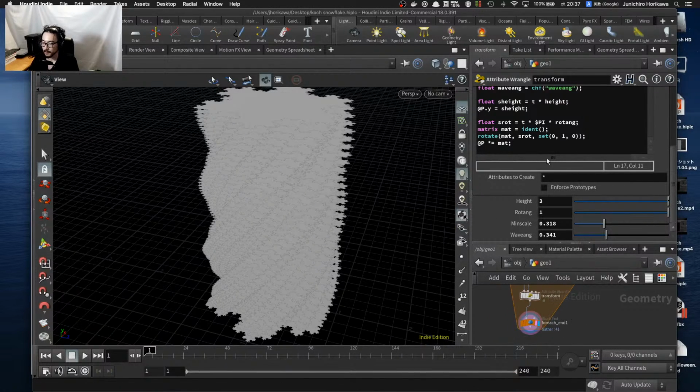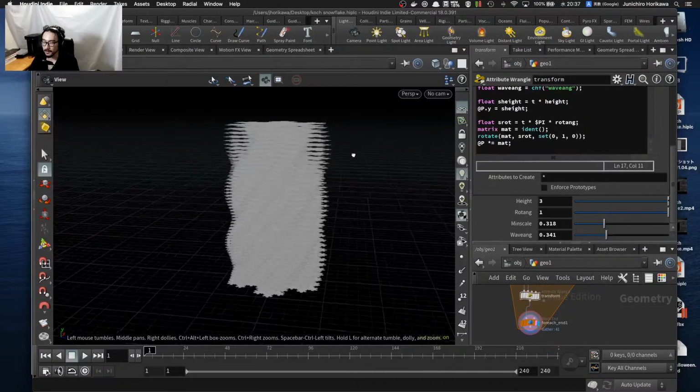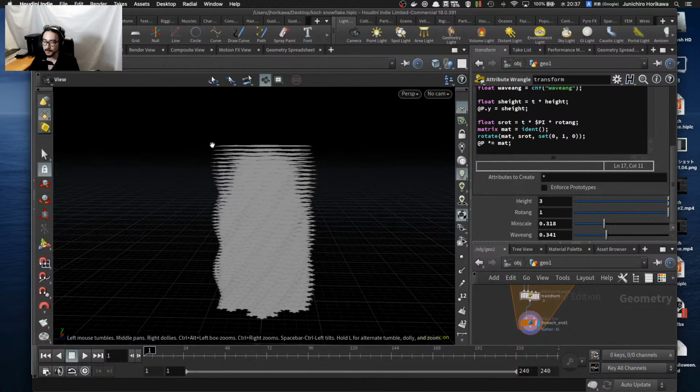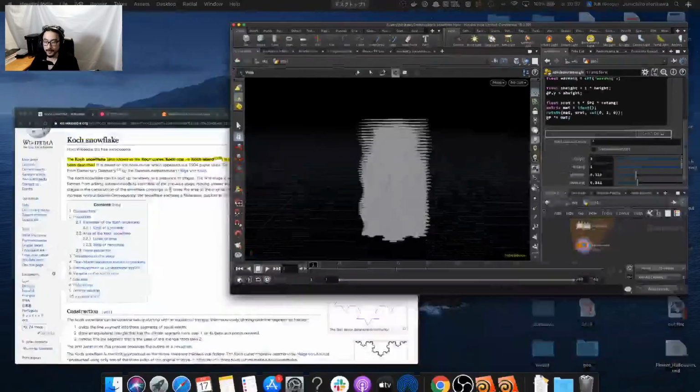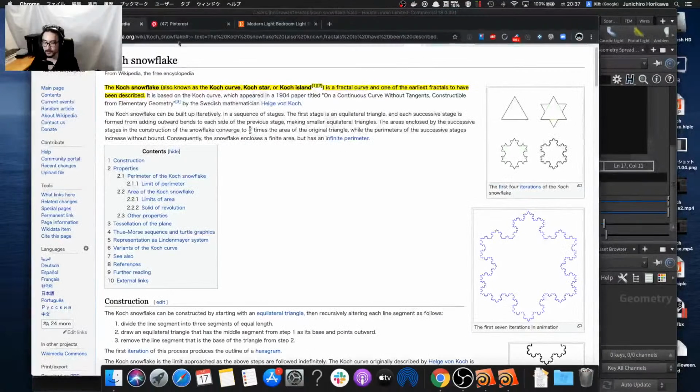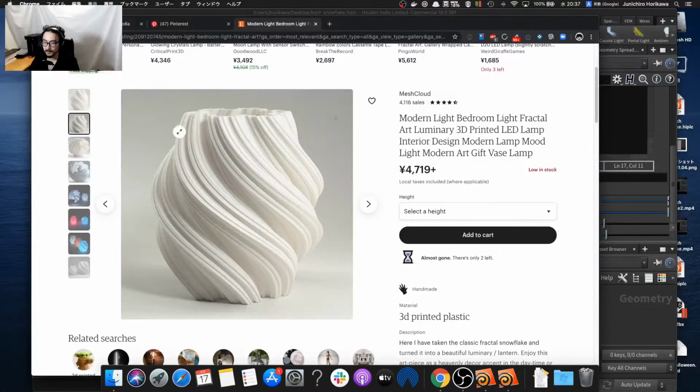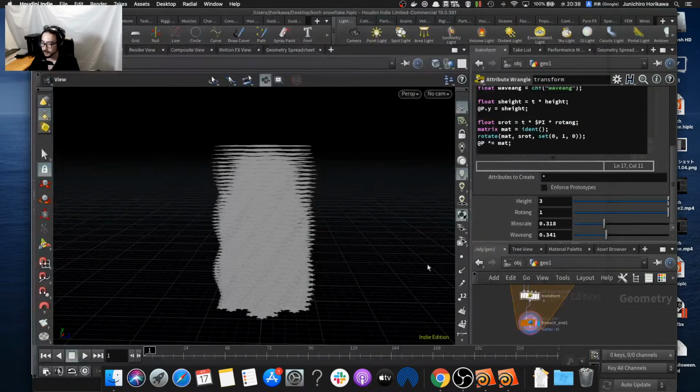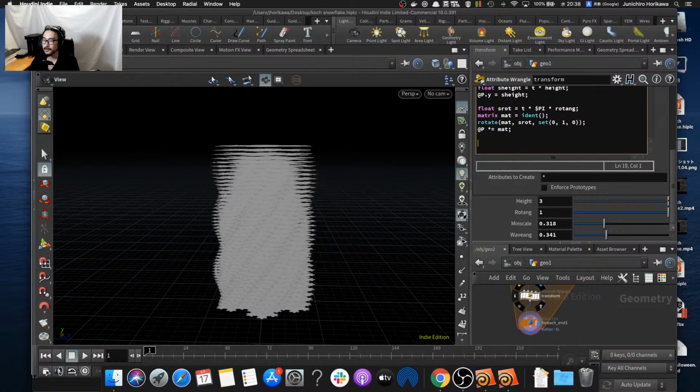Okay, last thing I would like to do is to create a section shape. So I want to create something like a wavy shape so that it looks like a vase, something like this kind of shape. For the simple section shape, I'm just going to use the sine curve, sine wave, because that's the easiest way to do that.